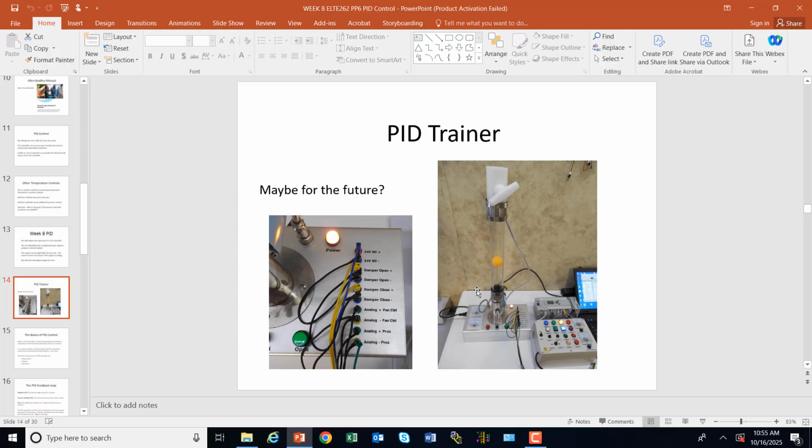But think of a heating and cooling process. You could turn on a heater to get the item warmed up, but if you overshoot by too much, you might have to turn on a fan to cool it down a little bit, at which point it would cause the heater to come back on, which if you overshoot again might cause the fan to come on. And so you might go back and forth a little bit, after a while, just a little bit of heating and a little bit of cooling, and finally it hits.